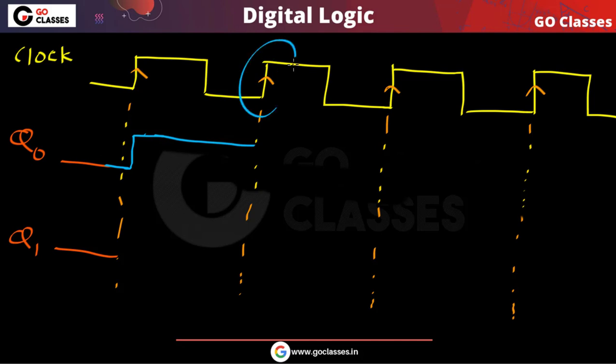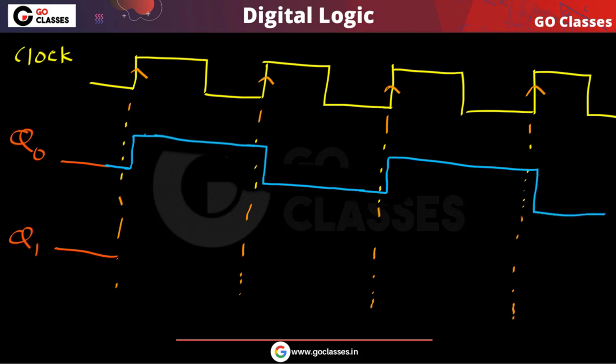With every rising edge of the clock, Q0 will toggle again, but there is a propagation delay, so it will happen like this. Again here there is a propagation delay, and here again. So this is the output waveform of Q0.